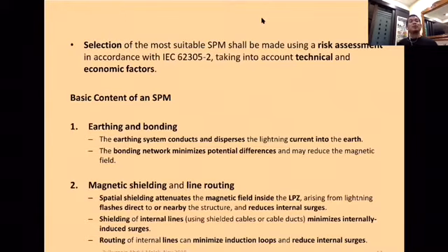You see, when you do the risk assessment, you define the zone. If you don't define the zone, maybe the exposure is there, then the risk cannot be limited. That's why you need to introduce zoning. So I hope you have the zoning inside your risk assessment, and the zone actually has a certain class, because the surge protection SPD can also go by class.